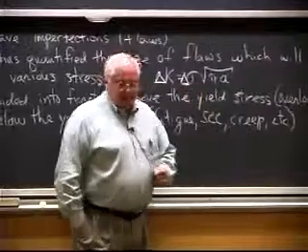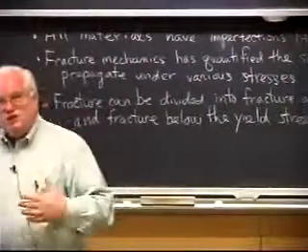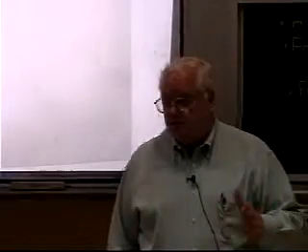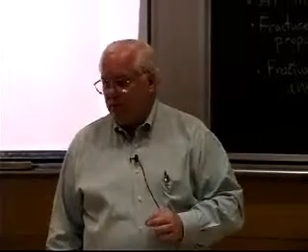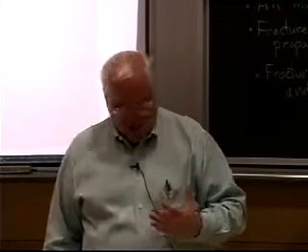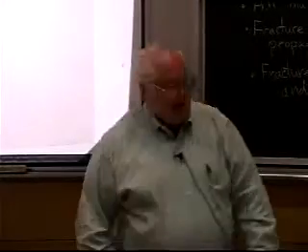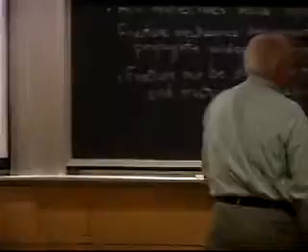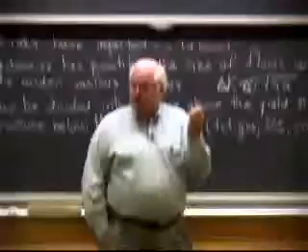And it's because a lot of times the stress that's actually in the part is not what you thought it was. Sometimes that stress is higher because of stress concentrations, the little notches we talked about. But many times it's because you have locked-in stresses within the part that you didn't know about or didn't suspect. In fact, that helicopter washer I talked about actually had residual stresses. Some of those parts just failed on the shelf.